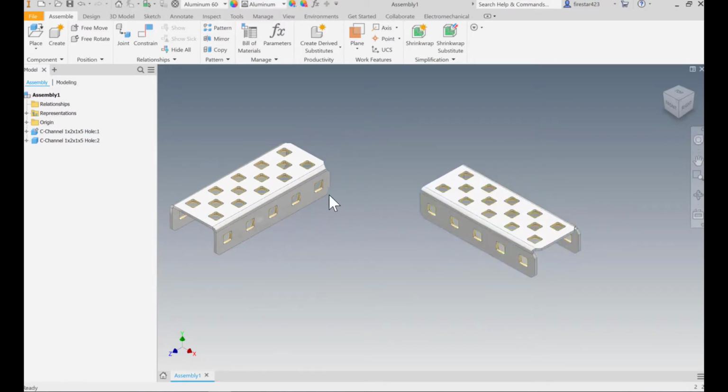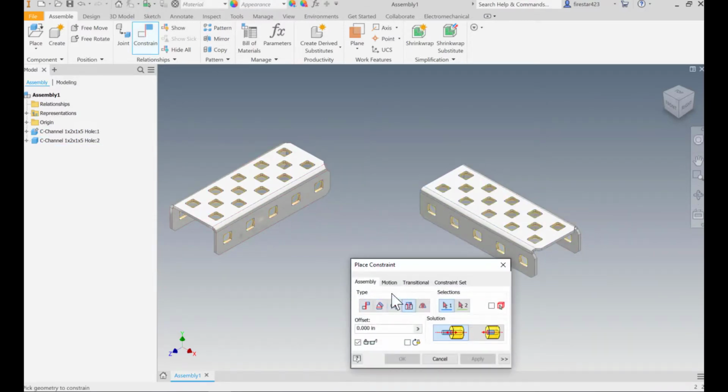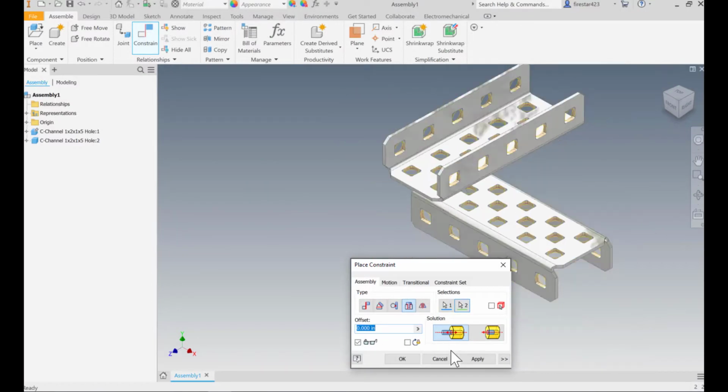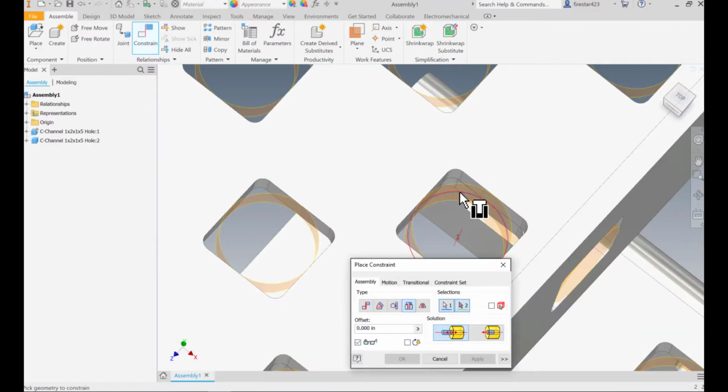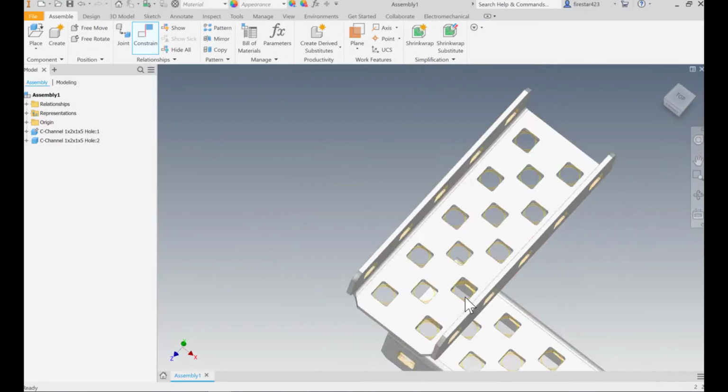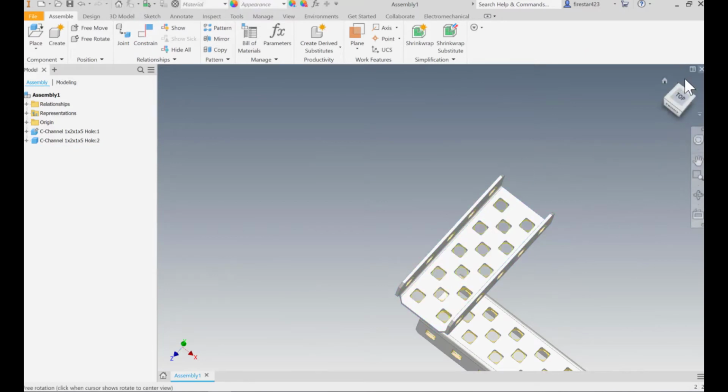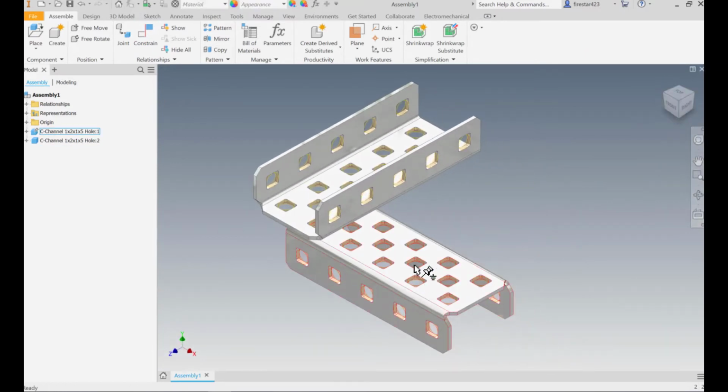This is useful because when we constrain two objects together, like such, and we add multiple constraints, that object can no longer move because it is constrained in place, and this one is grounded. It becomes exponentially useful when you have a big assembly with hundreds of parts, where if anything moved, it would cause quite the issue.